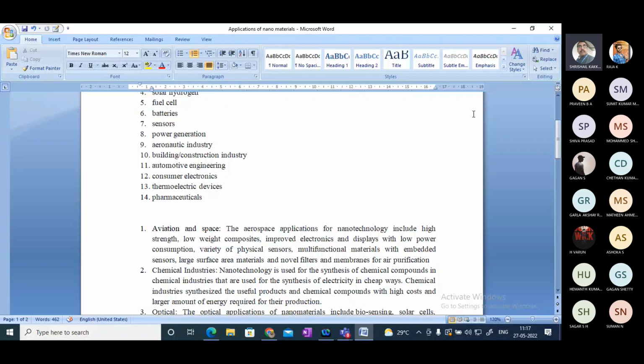But here, there are some kind of sensors. As soon as the engine is on, if the circulation is started, the engine will be cooled down at a higher rate. The thermal efficiency of the engine will come down. So what happens here? The nano-based valves may be used, which will be very sensitive to a particular temperature. Once the temperature of the engine reaches a particular temperature, it will act like an automatic valve, it will open and the secondary coolant will start to circulate in the engine.